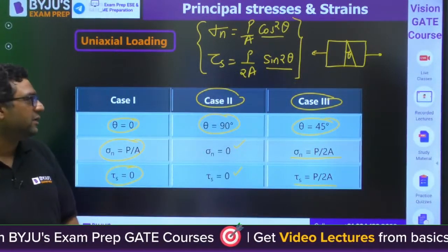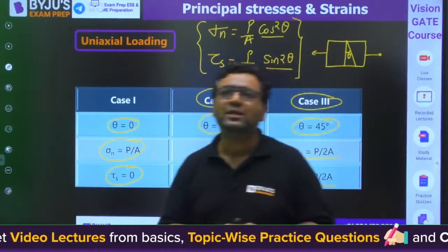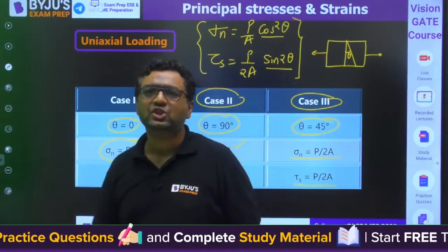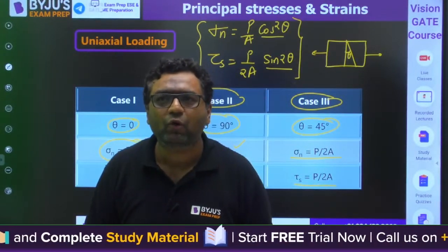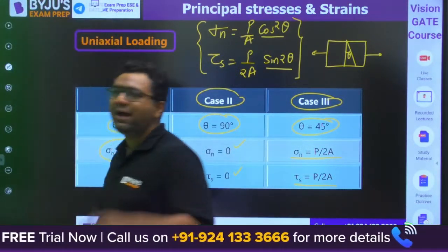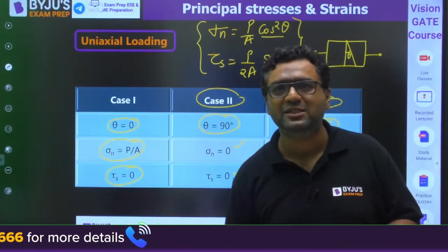What do you mean by that? At every plane, stresses are different. So we are not bothered about the stresses at all the planes. We are bothered about the stresses which are maximum in magnitude, because failure happens with the maximum stresses.